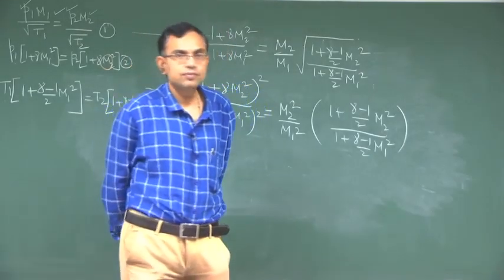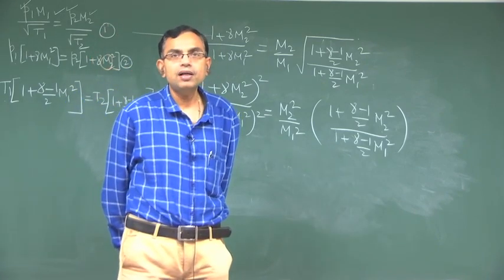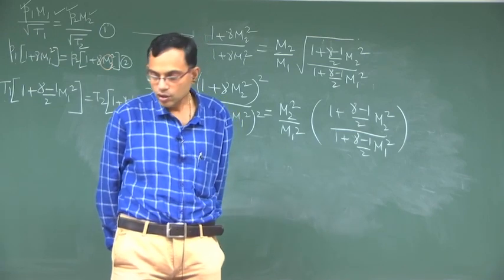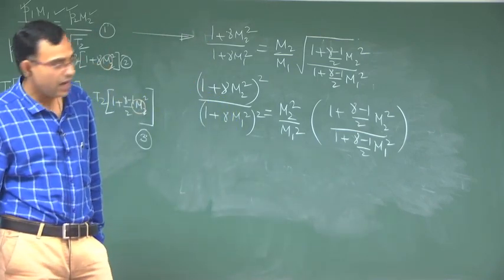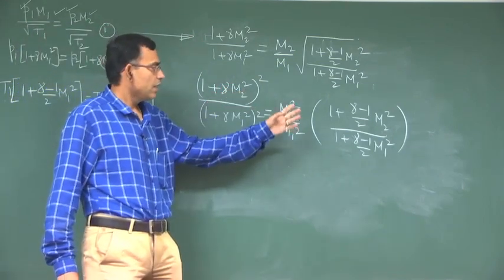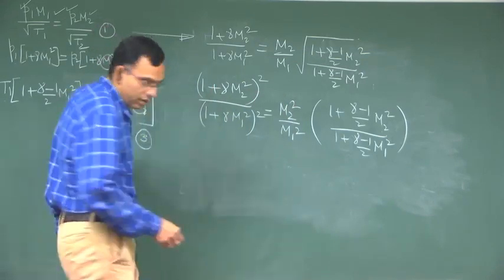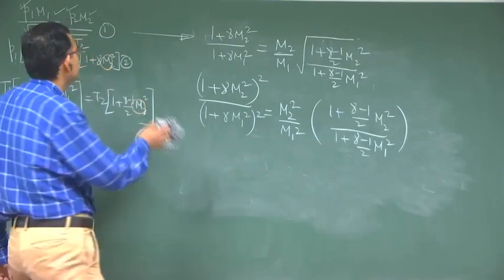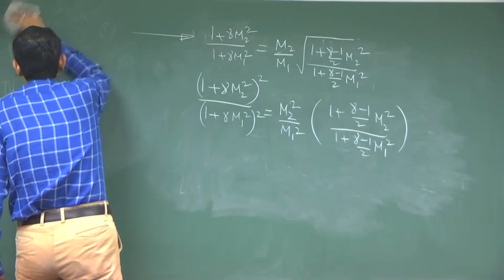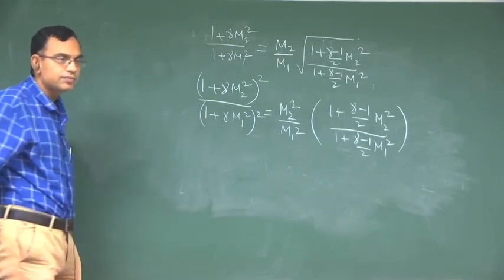In the previous lecture we were discussing the change in Mach number across the front of a normal shock. So, we arrived at this relationship, which relates M1 square with M2 square. For doing the remaining algebra, which in principle is straightforward, it is better that we walk through it so that we gain some insight.